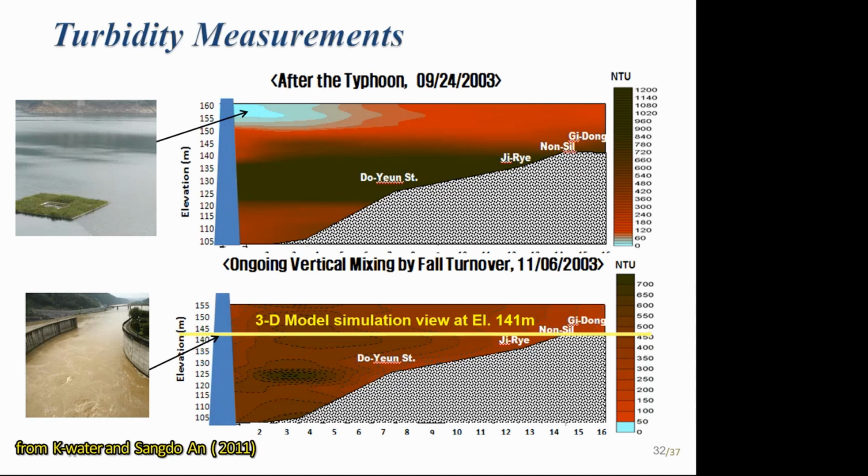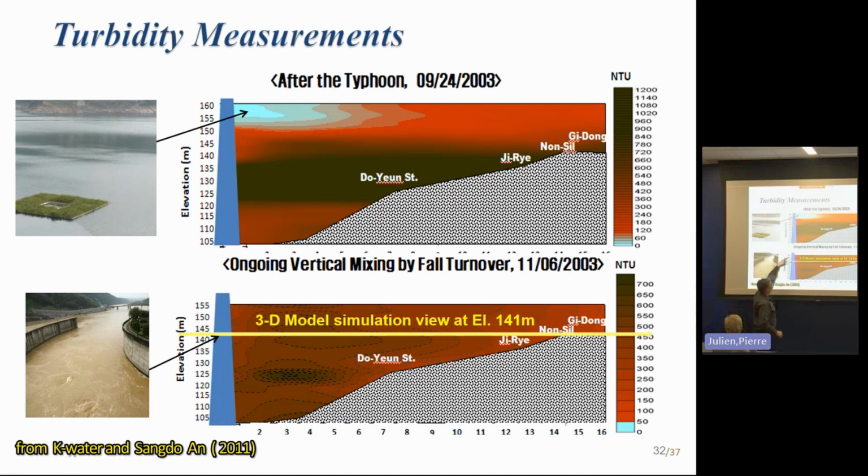Now, I want to mention something about sedimentation here, because we're looking at fine sediment, right? So fine sediment between silts and clays. For silts, you get the law for settling of particles. For clay, at 4 microns, the time it takes to settle over 1 meter is about 1 day. That's another order of magnitude, another one of my benchmarks. 4 microns, you want to talk clay: 1 meter is going to take 1 day to come down, right?